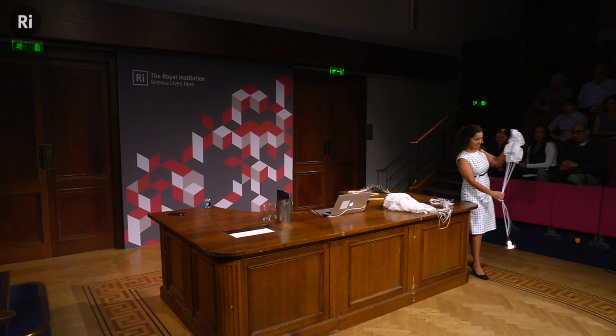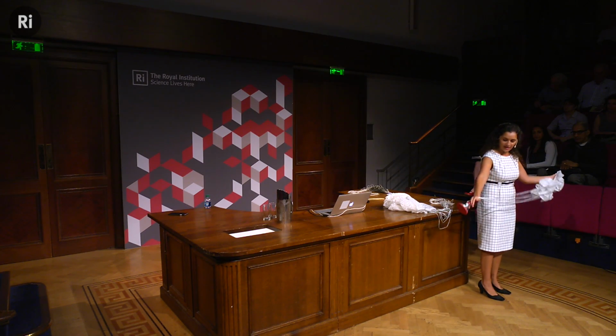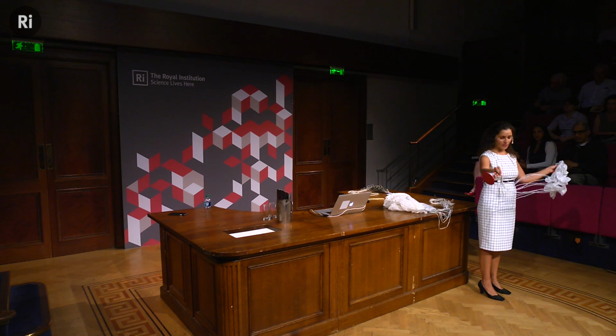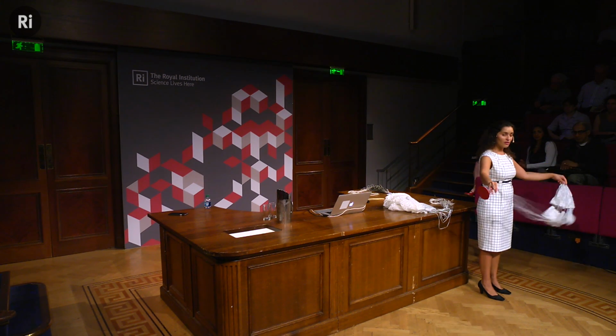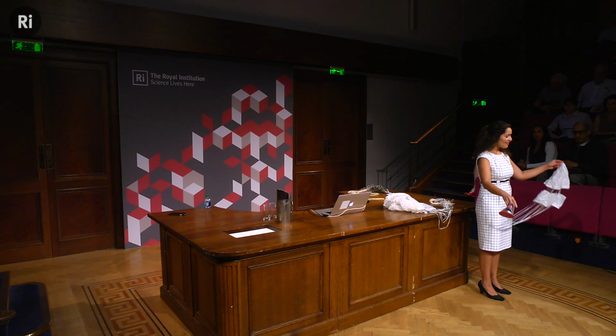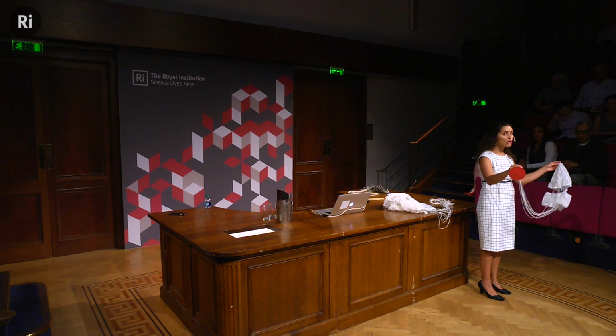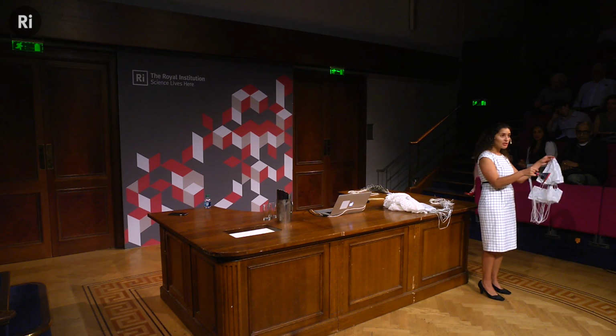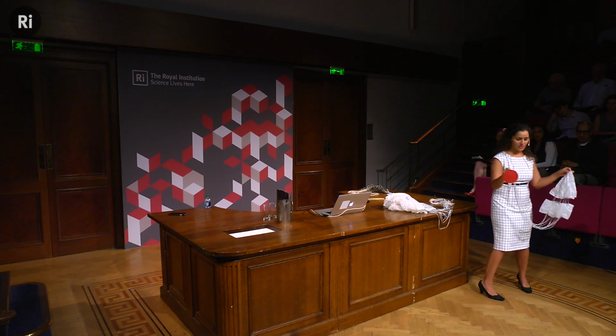And what we did was put this in a wind tunnel. In the wind tunnel, you have the vehicle, kind of like the MSL vehicle, rigidly mounted, and then you're flowing air through the wind tunnel. So it's flying as it would in actual flight. And then you're also making measurements of how much load it experiences. Is it collapsing and inflating like we had seen before? I'll show you some of those measurements.